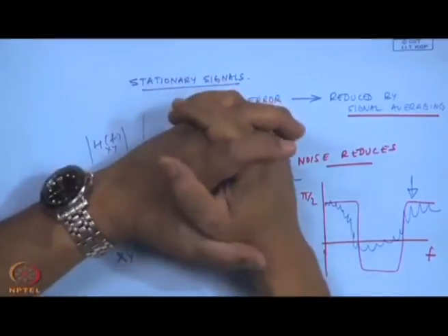Looking at the signal in the time domain, I will see very high amplitudes, overloads occurring repeatedly, though you do what is known as auto ranging. The features may be very high, the mean and the RMS values will be high.